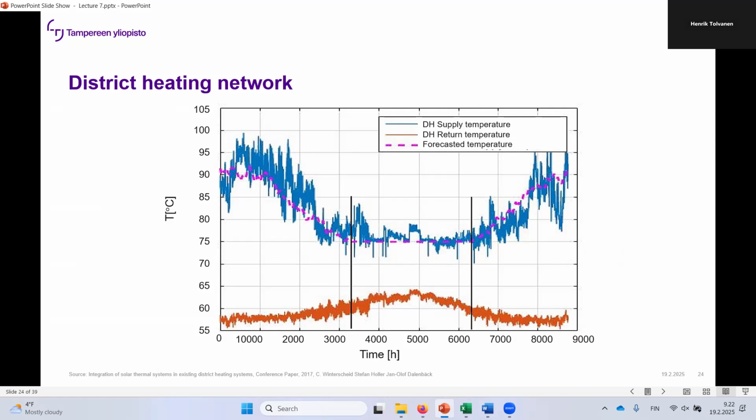In the summertime, there is less heat demand, so even though you lower this temperature, you don't extract as much power as during the winter time. The power consumed by all the consumers is the mass flow in the network and the temperature difference. Based on the temperature difference, you can calculate the enthalpy difference. So power is mass flow times enthalpy difference.